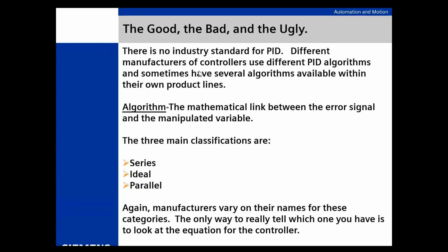I will say this in all my years of doing this. If I took PID out of brand A's controller and put it in brand B, it worked. Or it was so close it took very little tweaking. So in my experience, those algorithms aren't wildly different. Now, some manufacturers may claim they are.